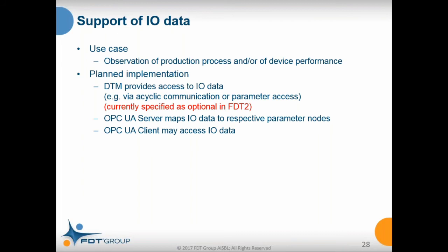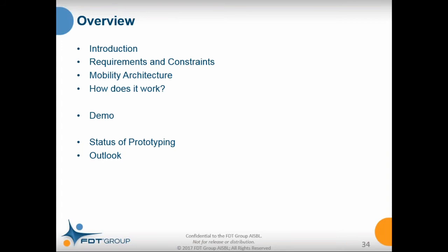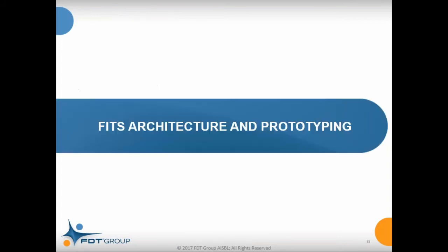So only when the DTM supports access to the I/O data via the acyclic device access services, then we are able to support also this use case. And then the OPC server may map the data to the respective parameter nodes in the parameter set, and the OPC UA client may then access the I/O data. So this very much depends on support by the DTMs.